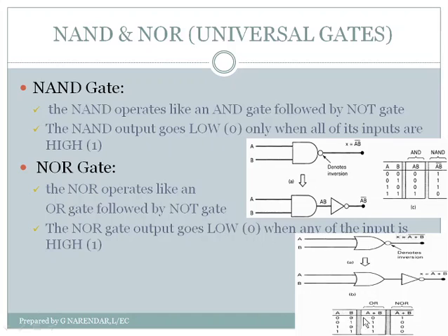And here we can obtain the output for each combination of the input. So if you see the first case where A is equal to 0, B is equal to 0, then the output of NOR gate, that is X equal to (A plus B) bar, if we substitute A equal to 0, B equal to 0, then X equal to (0 plus 0) bar, and 0 plus 0 is 0 according to OR operation, and 0 bar is 1.